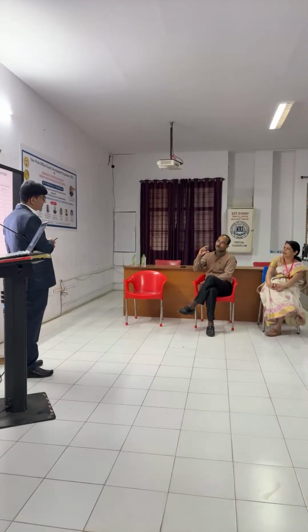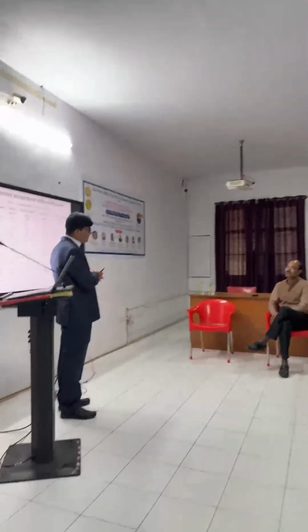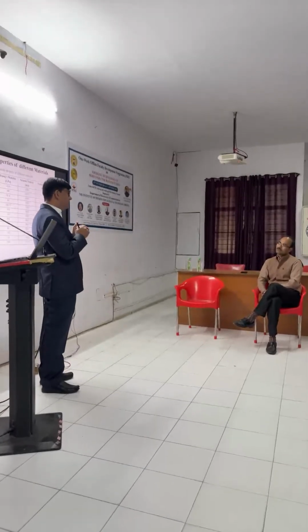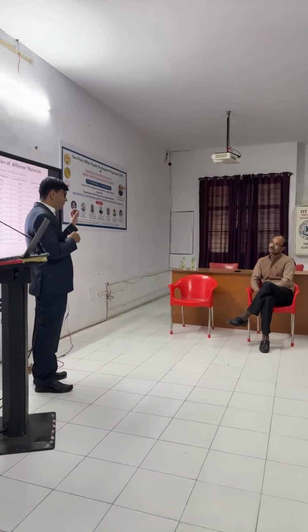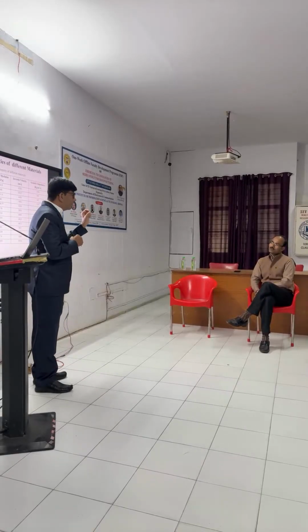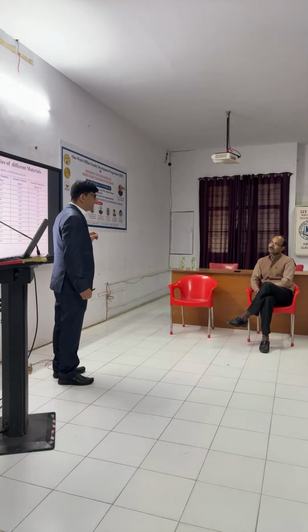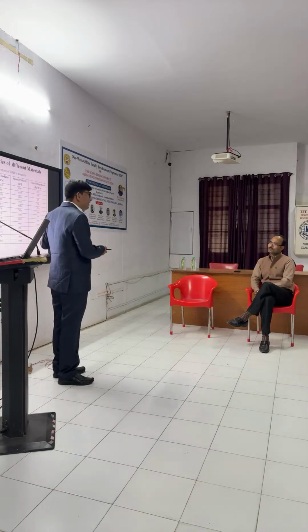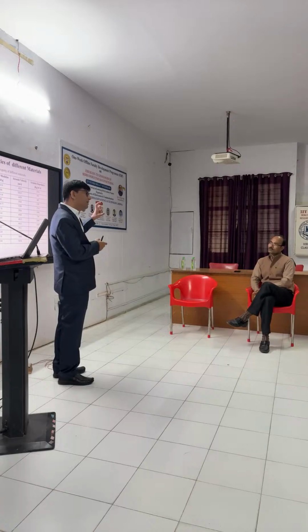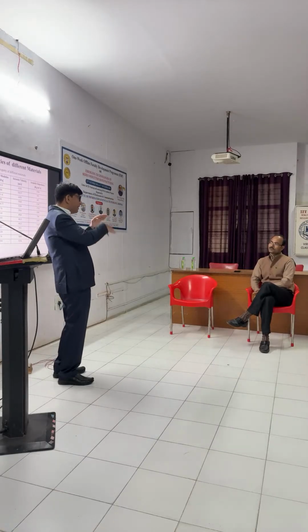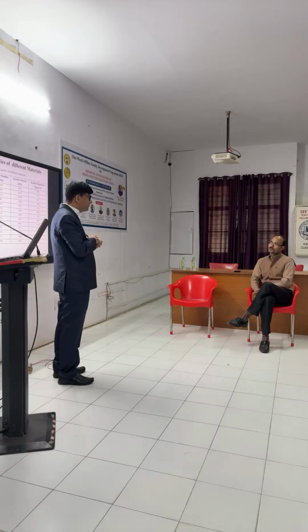Yeah. Okay, so what is the limitation for the thickness? There is no limitation, sir. Because see, you can't go beyond a particular thickness. For example, if you want to deposit 0.2 micron thickness, that is 200 nanometer, you can't manage your resonance because it requires bulk. Your signal will travel back and forth in your piezoelectric layer. There is this kind of minimum and maximum limit. See, if we want to go for bulk acoustic, at least we have a 0.7 micron.